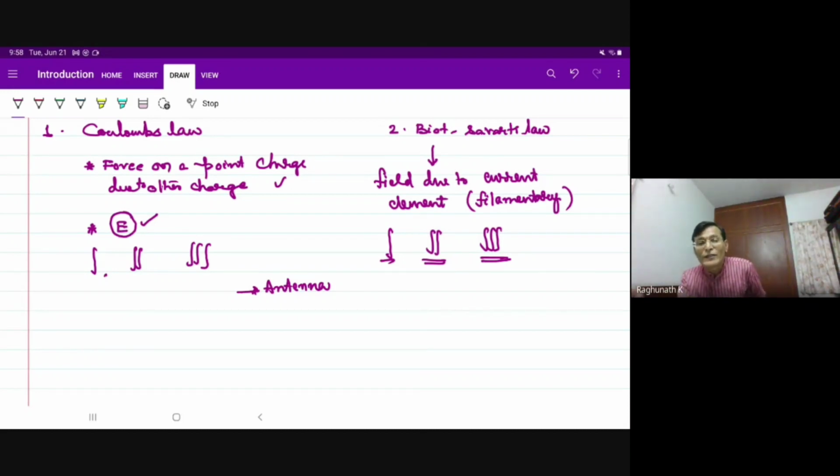A low pass signal, when we speak, an audio signal converted into an electrical signal, will never be given as the input to the antenna, because the antenna height required will be in kilometers. Impracticable, rather. Whenever I want to use the free space channel, I want to use an antenna, I will go to the radio frequency spectrum. Radio frequency is one that can be converted into an electromagnetic wave by using a realizable antenna.